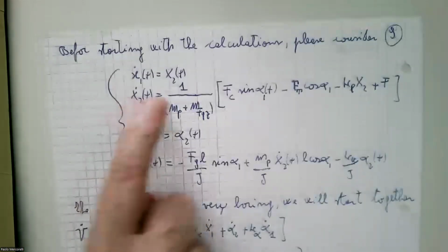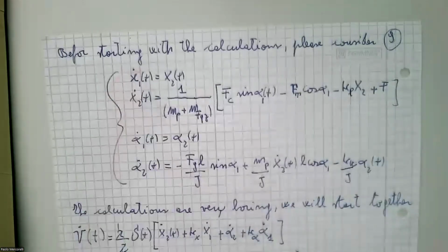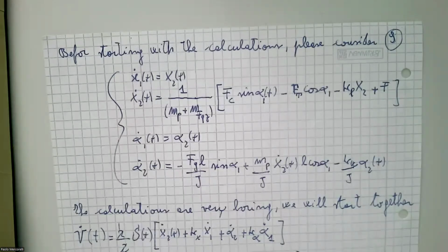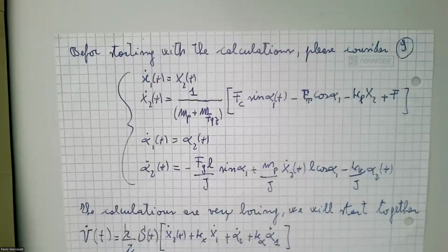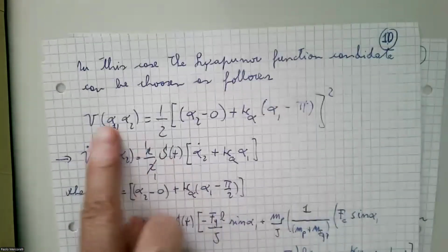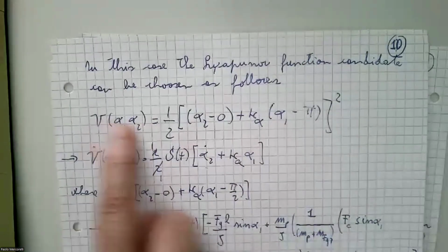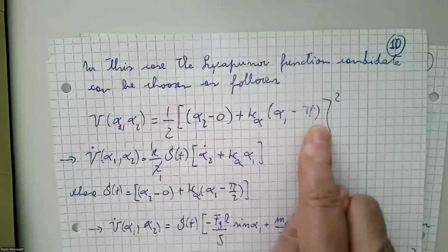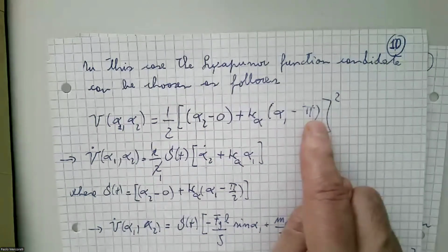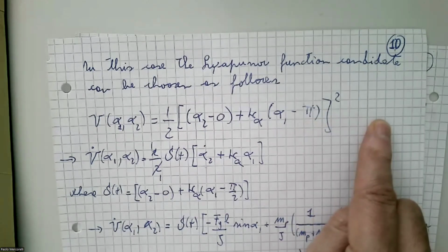This means forget the stability of x1 and x2. x1 is the position, x2 is the velocity of the car. Forget this in the Lyapunov function. Forget x1 and x2. Don't consider this, because if I consider it, I cannot travel. And just consider as a pseudo Lyapunov function, Lyapunov-like, just to stabilize the arm, neglecting the position of the car.